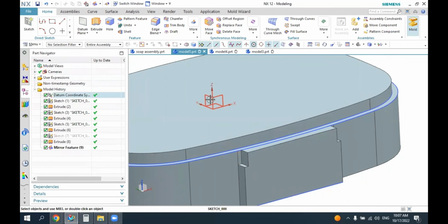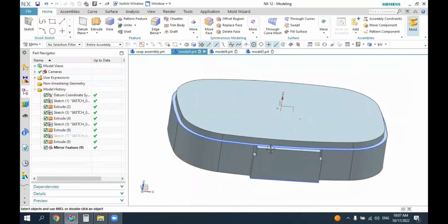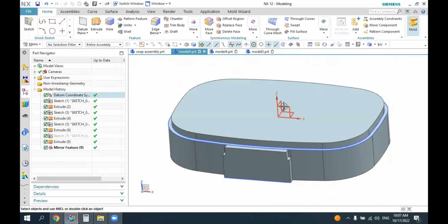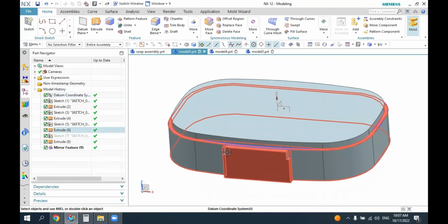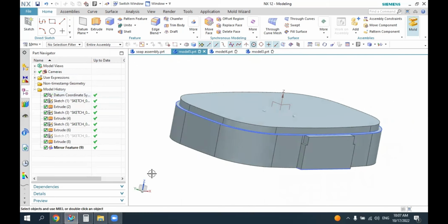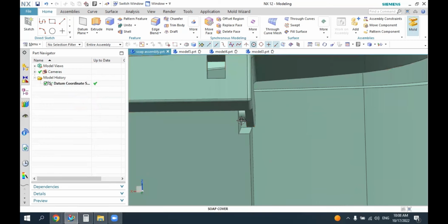That's why it is important when you are creating your model in a symmetric way. It will be helpful when you are making such symmetric elements. So this reference system will be helpful for mirroring your feature. If you don't make your system in a symmetric way, you are not able to mirror this one, so it will be a mistake. So we created this one, and let's go on here. We have this system, which was created with a 3 millimeter diameter.